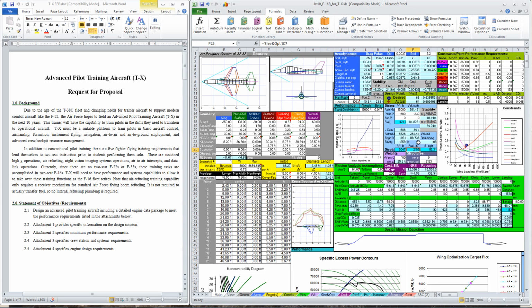Well, at this point, the airplane looks just a little odd. It's a little long, and the horizontal tail's too big. Those horizontal tails should be closer to a third the size of the main wing. Let's drop the horizontal tail size down to 80. And let's shorten the fuselage a bit. I think we can safely do that.